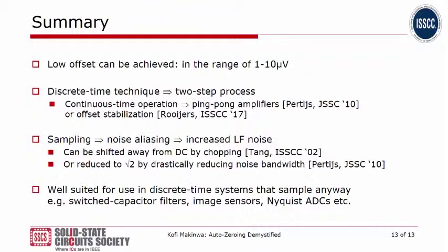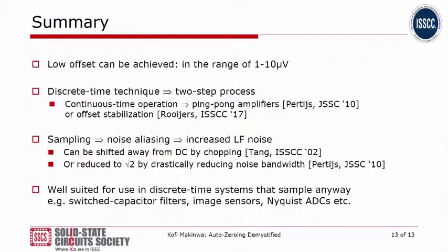Last but not least, I should stress that despite some of these issues, auto-zeroing is the low offset technique of choice in discrete-time systems where you are basically sampling anyway. Because you're sampling anyway, these issues of noise aliasing and so on already exist in your system. And therefore, you can add on auto-zeroing without any further penalty. And therefore, auto-zeroing is well suited for use in switched-capacitor filters, image sensors, Nyquist ADCs, and the like.